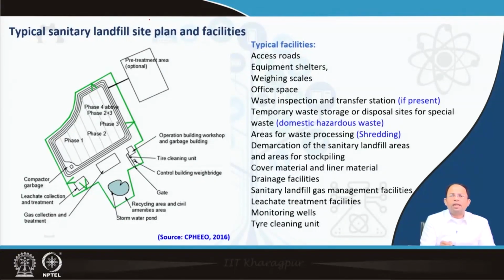So this is how a landfill site looks. You can see there are phases: phase 1, 2, 3. We have discussed phases earlier, but we will discuss them further. These phases are designed because the entire volume of waste that needs to be stored in the landfill accumulates over a period of years. So we design each phase for maybe 1 or 2 years, and we only work with that part of the landfill. So as you can see, these are the phases of the landfill.